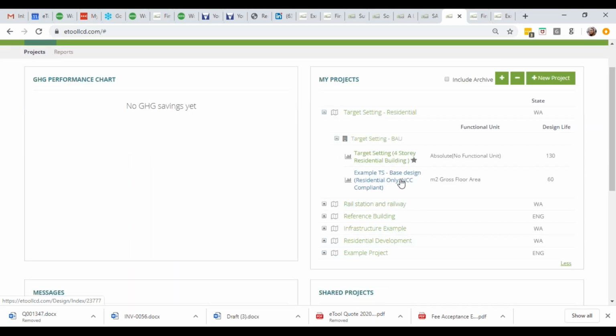For example, here's residential building, full story, NCC compliant. So it already has some minimum requirements in place, and it's a whole building. So all you need to do is simply to adjust areas and maybe replace one material through another in templates if this is not what you were planning to have in your concept. But this is really easy and fast way to run some strategies.